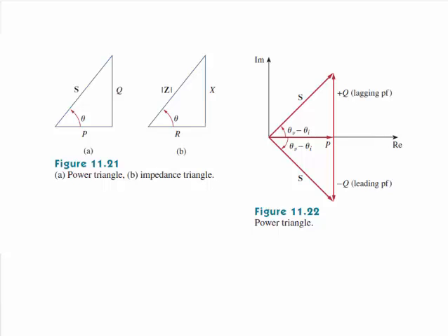I think the most difficulty in this part of this chapter is really the fact that you have to keep track of all these complex numbers, and the textbook likes to mix up the angular versus the trigonometric versus the complex representation of all of these quantities in a circuit. Other than that, you are applying your Kirchhoff's laws as you already know them for loops and meshes. You're just having to keep track of the math that's involved there, and whether you're using peak values or RMS values when you do your equations.